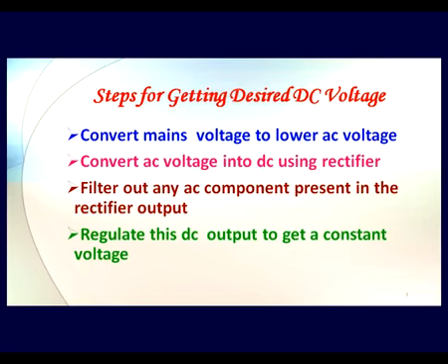But that rectifier output sometimes has some AC component present within it, as will be very clear when we discuss the rectifiers. Then we have to remove that AC component and this is done by using a circuit that is called a filter. Filter, as you know, the name is very clear. We are trying to filter out something. Here what are we filtering? We are filtering the unwanted AC, or the frequencies of 50 Hertz or 100 Hertz or whatever are available. They should be removed. So that is the filtering process we subject our voltage to. So then we get a DC voltage.